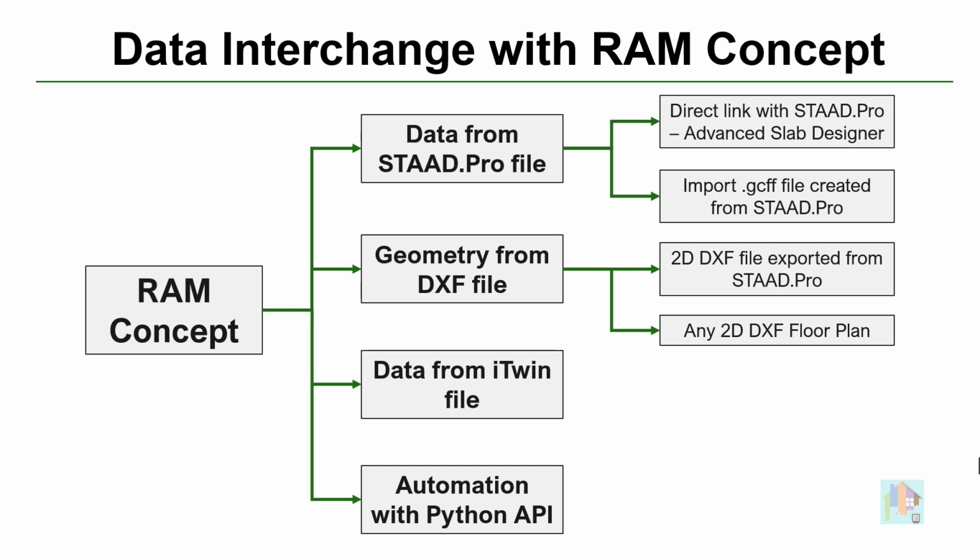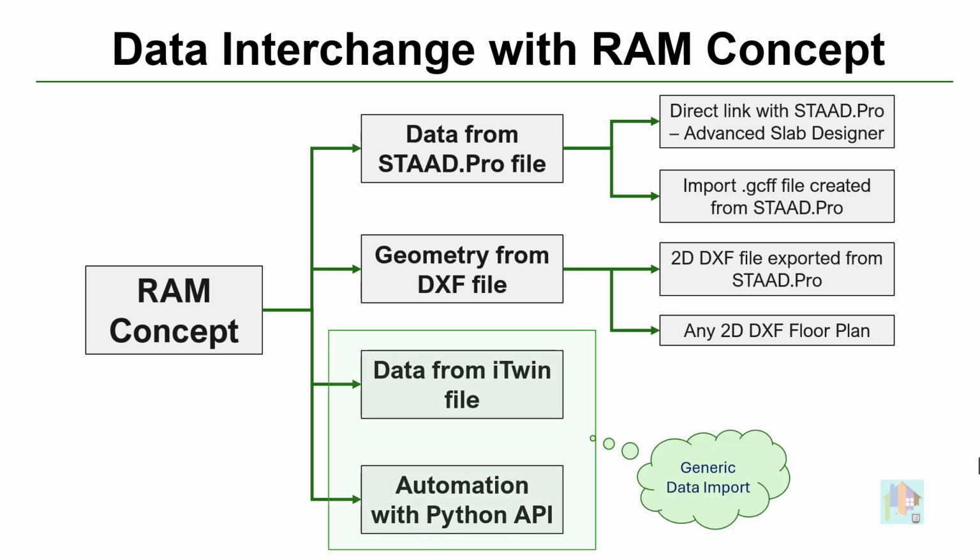Apart from this, we can export any floor plan from STAAD as a 2D DXF file and import that in RAM Concept. There are a few other approaches using which we can not only import data from STAAD but also from any application including Open Building Designer, Revit, even from an Excel file. How we can transfer the floor geometry to RAM Concept, that I'll cover later.